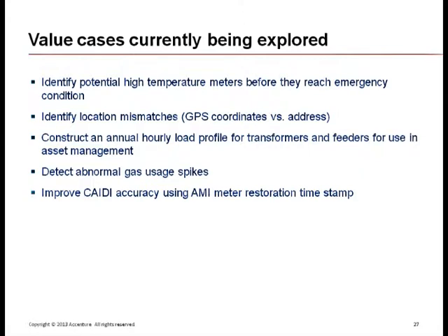So we are converting address XY coordinates to equivalent GPS coordinates and using them as reference points, comparing them with meter GPS coordinates. And if the difference is more than a threshold, we are planning to do field investigation to fix meter GPS coordinates. Next value case is construct an annual hourly load profile for transformer and feeders for use in asset management.